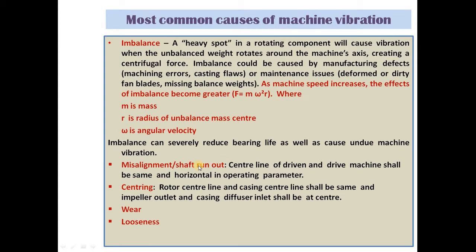Misalignment also creates machine vibration. We'll discuss in detail now. Centering: the rotor center line and casing center line must be the same. If this center line is not the same, then the flow will not be streamlined. Then flow induced vibration will come. So centering should be perfect.